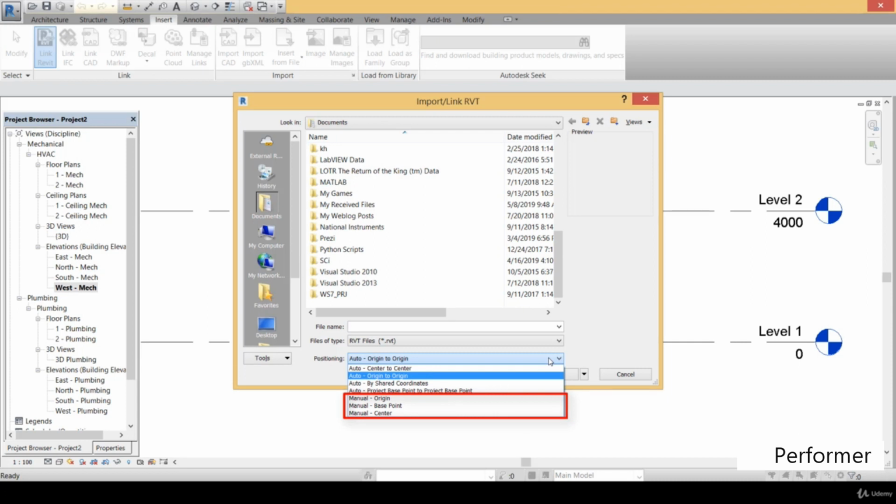And we then recommend to choose the automatic option anyway, because you may make some mistakes when you specify the layout coordinates on the X and the Y axis, for example. So if you insert the project at a specific coordinate, and another designer who is working on another part of the same project has inserted the layout at other coordinates with respect to the coordinates that you made, there will be a shift in the design between you and him, and this will be a problem. So instead of the manual insertion, we prefer the automatic insertion.